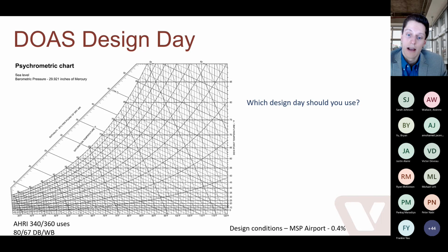The most common would be your dry bulb design day. But there are others. There's a dehumidification design day, and a few others that are similar. But how do we know which one to use, right? So the first one, cooling design day or dry bulb design day. And in this example, I'm using Minneapolis because that's where I'm from. So bear with me on that. Okay, that's a pretty common design day here.